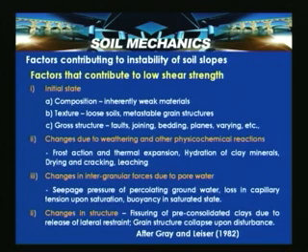Lateral pressure, water in vertical cracks, freezing water in cracks and root wedging can contribute to higher shear stresses. So, the major factors, if you summarize, are the removal of lateral support, surcharge, transitory earth pressures, removal of the underlying support and lateral pressures. These factors contribute to the higher shear stresses and ultimately cause instability to a soil slope. Having seen those factors, let us see what are the factors that contribute to the low shear strength. Ultimately, they cause instability to a soil slope.